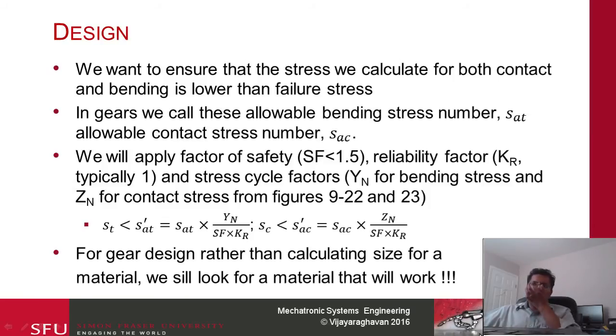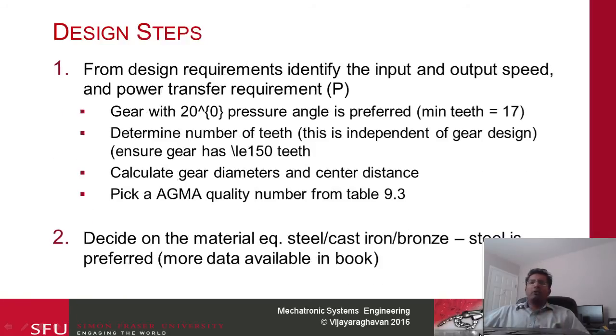These would be the typical design steps. First, from the design requirements, we identify the input and output speed and the power transfer required. Since we're going to use a 20 degree pressure angle, sorry, this should be 20.